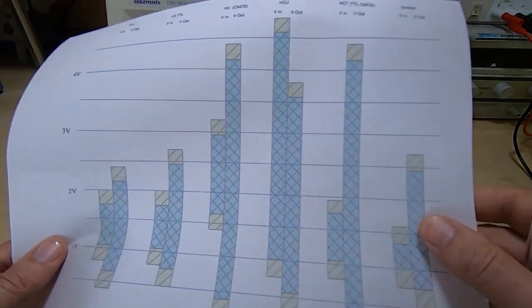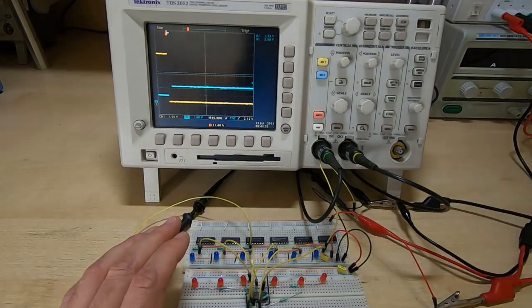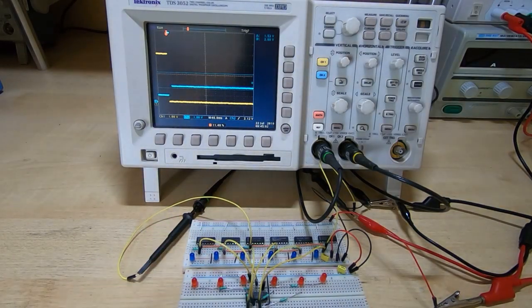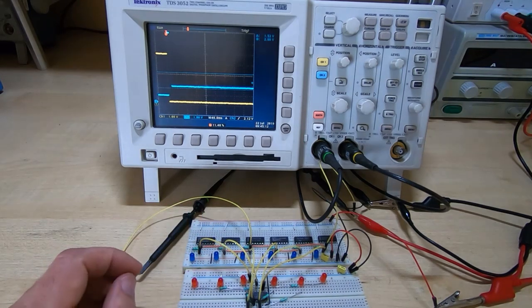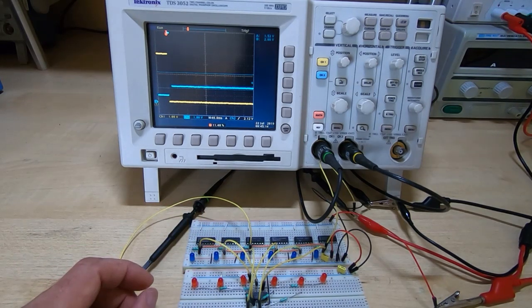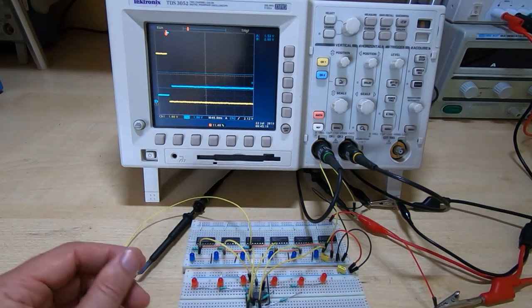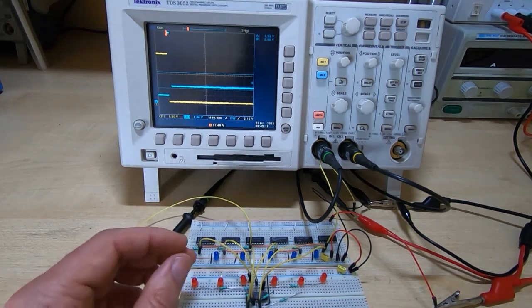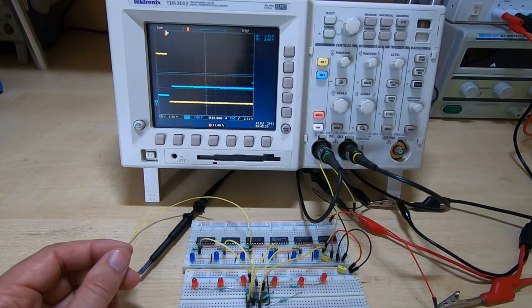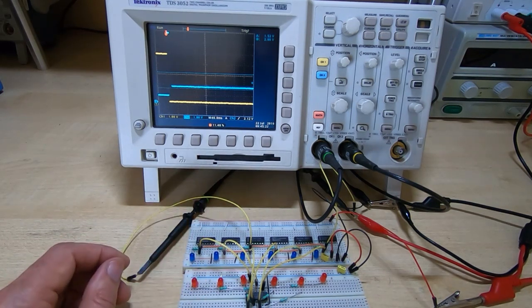So what I've done is, as I say, set all these up on a breadboard so that we can supply them with a common clock signal. They're all on the same power supply, and they're all feeding inputs to standard 74 LS gates, which is kind of what you normally see on the Altairs when you get a mix and match. It's one of these feeding an LS or one of these feeding an HC or something like that, but the point is it's a mixture rather than all being a consistent type.